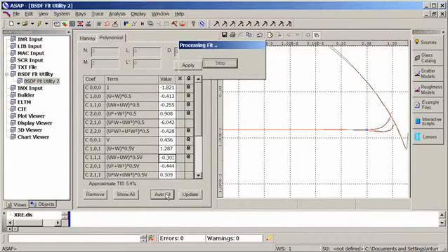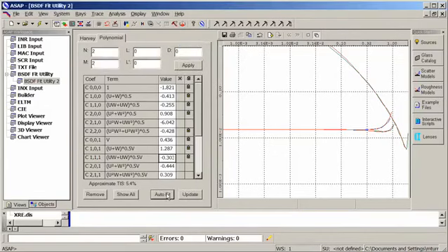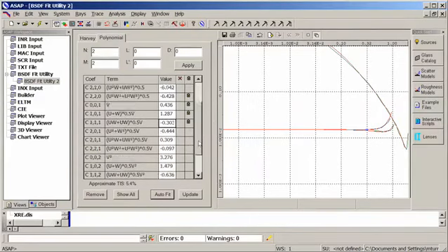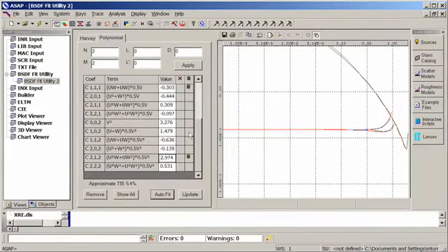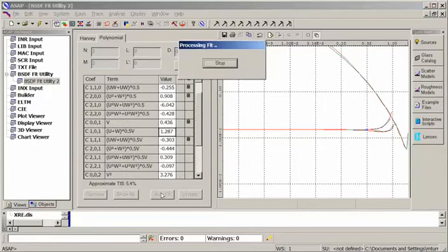And as you can see at this point in time, considering that scatter measurements within even 10% are considered reasonable, I would probably be quite happy with this fit at this point in time. I could, of course, continue to iterate through to try to maybe get a closer fit at the 80-degree angle of incidence. And again, you do that simply by locking and unlocking terms and then letting ASAP apply its auto-fit